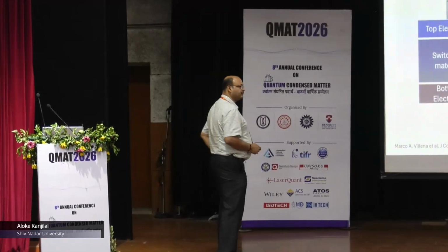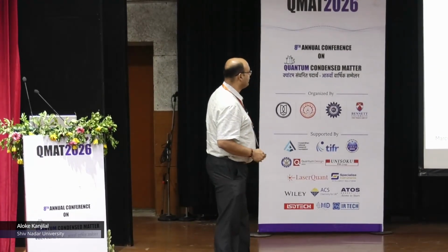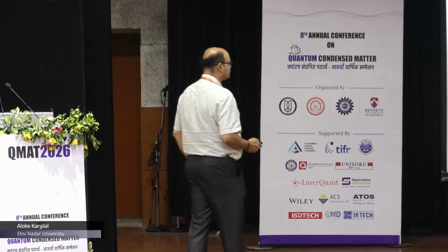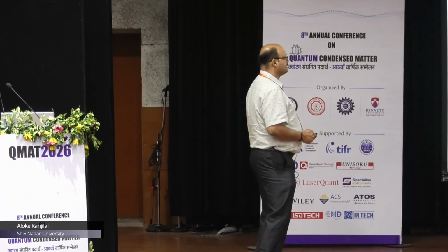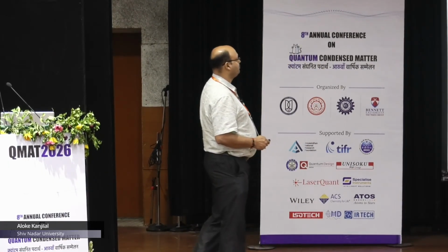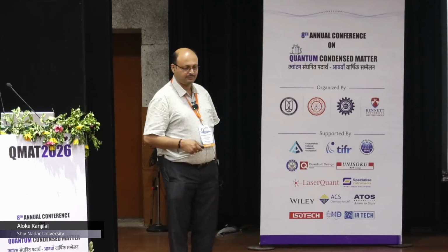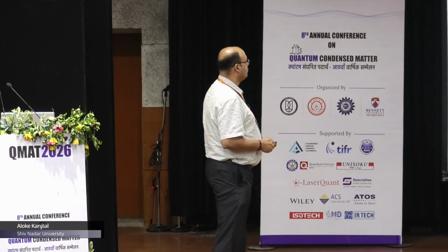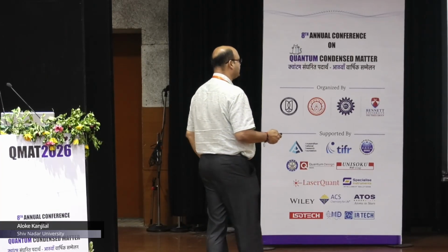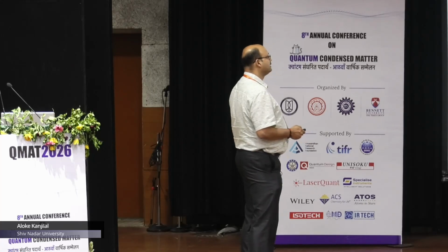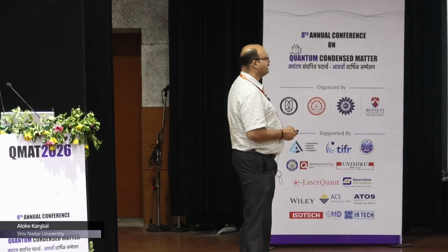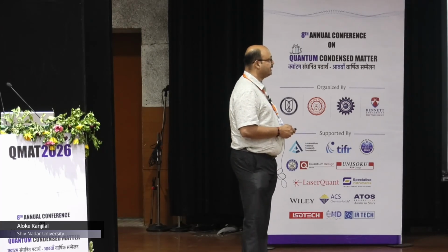Among the different models in the literature, two are very popular: one is cation-based and one is anion-based. Generally, if your electrode material is active, when a potential is applied between the two electrodes, the cations move inside and form a filament, and that is called the set.